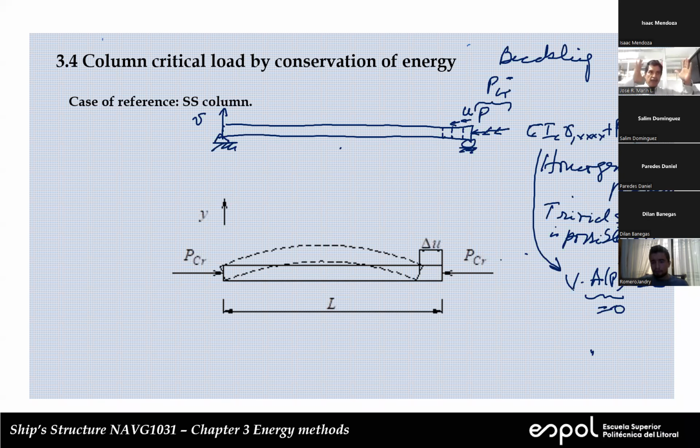Okay, we apply a compressive force so that this constant is 0. That means that the amplitude of the lateral deflection could be anything. That's what we are finding. Now, what happened before, we are not going to consider. What happens if we are just a little bit below and we increase the force by this little amount, and the buckling occurs, that's what we're interested in. That's the situation that we want to calculate. So in this case, the force is P critical, right? We were a little bit below, but this little amount is negligible. So basically we are at P critical here.